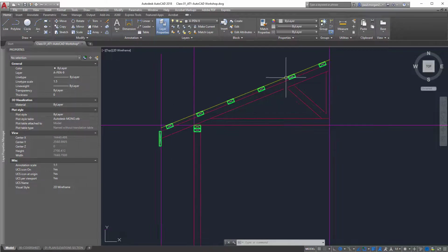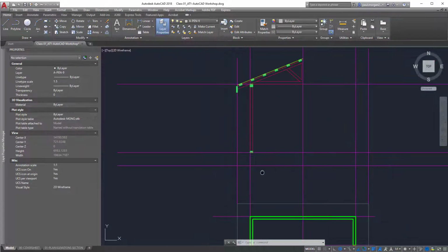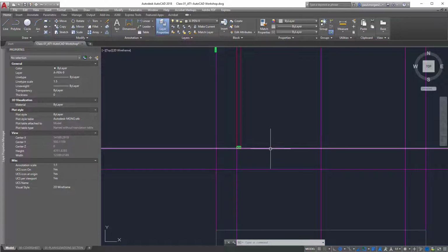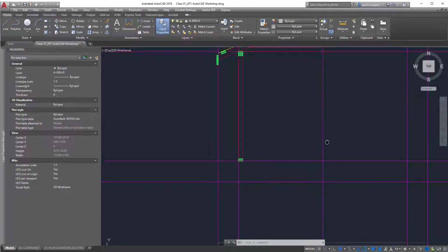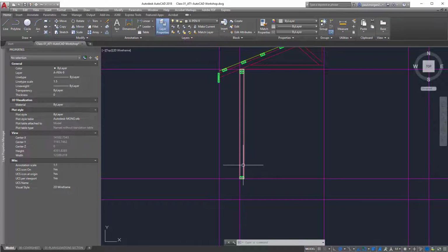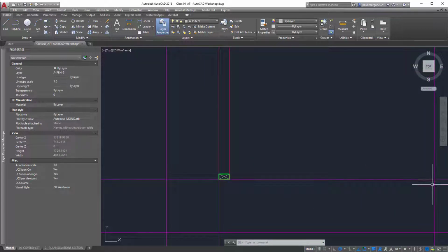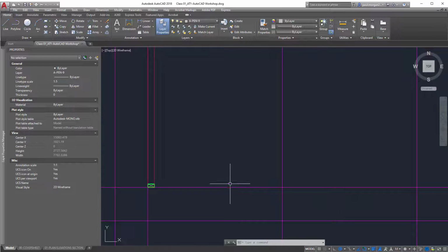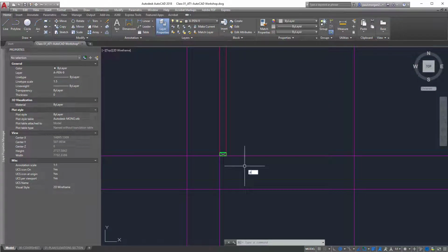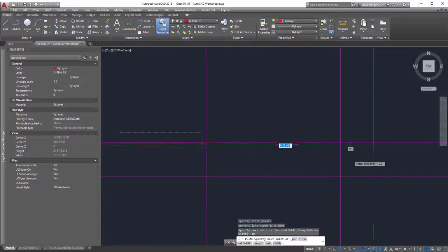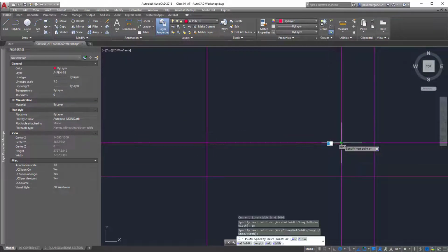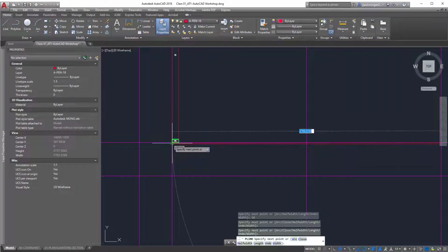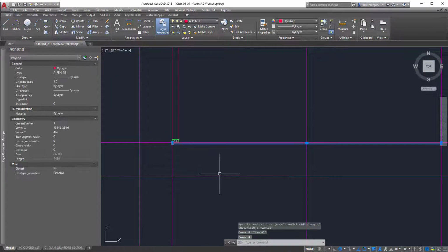All right, so we're now complete with the roof structure, but let's think about the footing detail. So again, the footing detail I'm going to do once here and then mirror that across. The flooring itself I'm going to draw as one object because I don't want to have some sort of break split line in between. I just want to draw it as one continuous line. So I'm going to use polyline, go back to my pen 18 layer, and I'll start here, draw down 18 mil, come across all the way to the other side, up and around. So that's one completed polyline, like so.